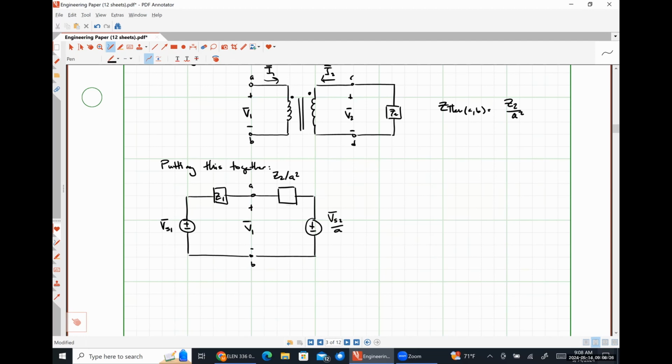All right, so this allows us to effectively convert a circuit where we have something potentially gross on one side of our transformer or the other into something incredibly simple that we can analyze using very basic single phase circuit analysis. So without too much math, because you guys are getting bored with it and I know I'm getting bored with it, what do you think would happen if we needed to reflect something from the primary side to the secondary side?